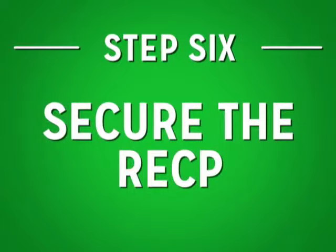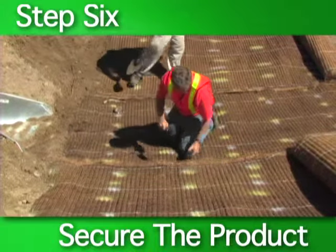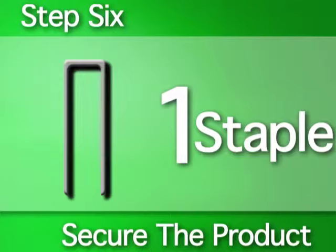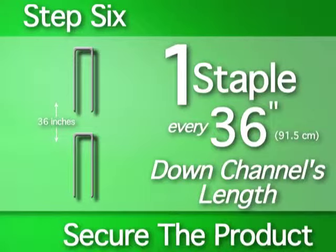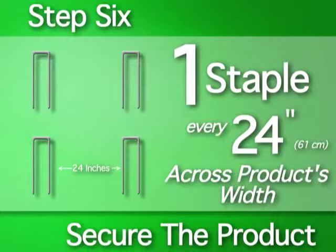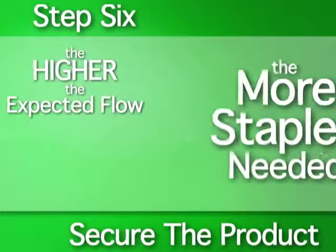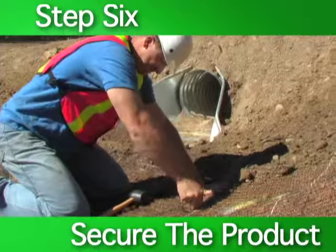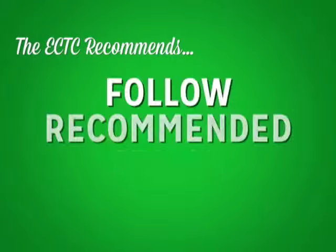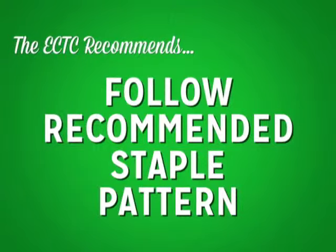Step 6. Secure the RECP. The next step is to secure the unrolled RECP to the bottom of the channel. A typical installation requires a minimum staple pattern of 1 staple every 36 inches down the channel's length, accompanied by 1 staple every 24 inches across the product's width. The higher the expected flows, the more staples needed. Staples can be applied either by hand or mechanically using a staple gun. The ECTC recommends that you follow the manufacturer's recommended staple pattern.